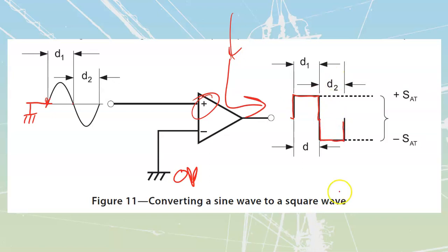It's not quite a perfect rise, fall, rise like that. What it has, in actuality, is a tiny little bit, and then it goes up, and then it drops down, a tiny bit, and then it goes down, etc. So for a couple of tiny, we're talking microseconds, if not nanoseconds, we're going to be hovering at that 0 volts, where it's neither putting out a positive nor a negative because it's not high enough to drive that out. But it's going to be really, really tiny.